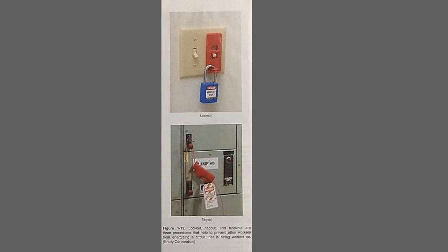Overhead power lines can create one of the most hazardous situations. These lines are high voltage conductors that are often uninsulated and low to the ground. Carrying a metal ladder or conduit near these conductors should be done with extreme caution.